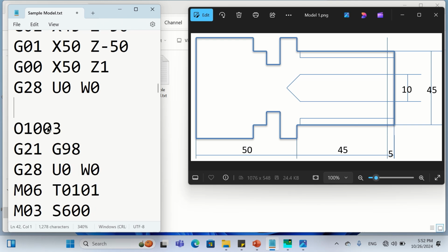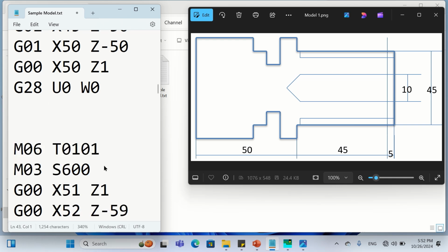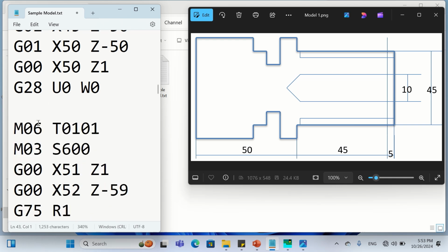Now, for the third program, we have written the grooving operation. So now we need not give another program number. We will remove till here. It is already in the home position. This also we will remove till here. Now here it is at home position. From home position it is asking for automatic tool change, T0101. So T0101 we already gave, that is for the turning operation.